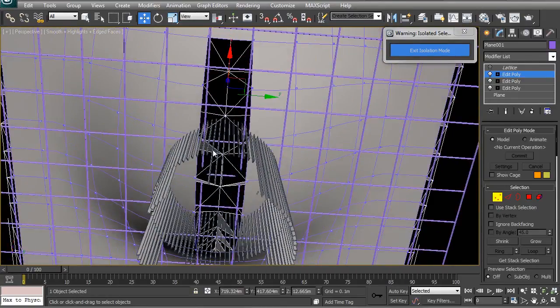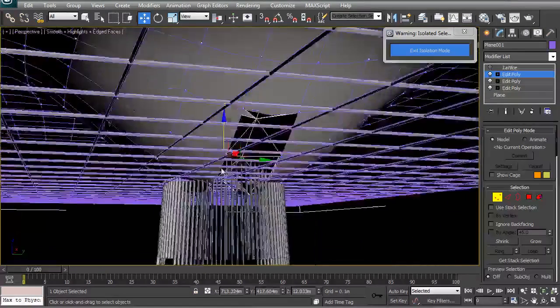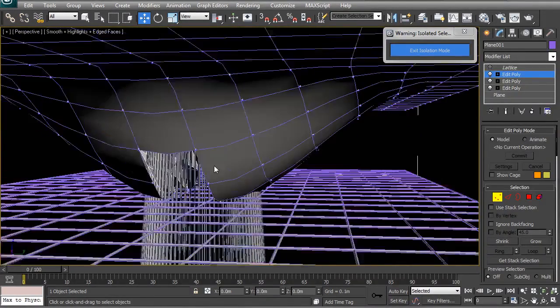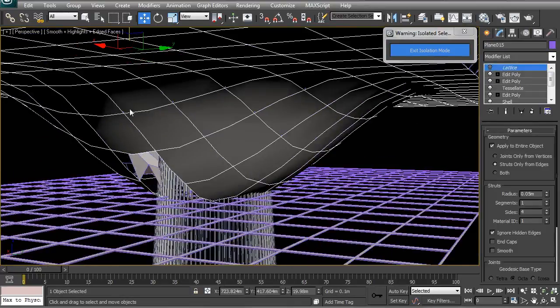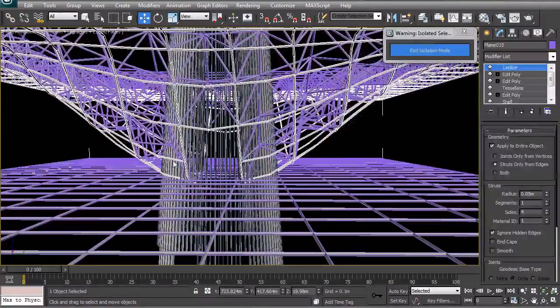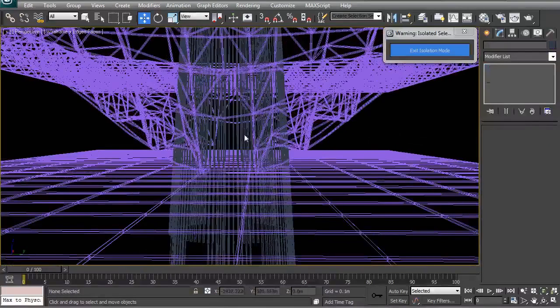Space frames essentially have their strength through the fact that everything is acting in unison, and once you start cutting holes out of it, it really defeats the point. But we also do know that we have to somehow work between a design and a structure. So very often things like this can be compensated for by adding extra structural steel around this portal and working around the fact that you need to have this portal as a design element.